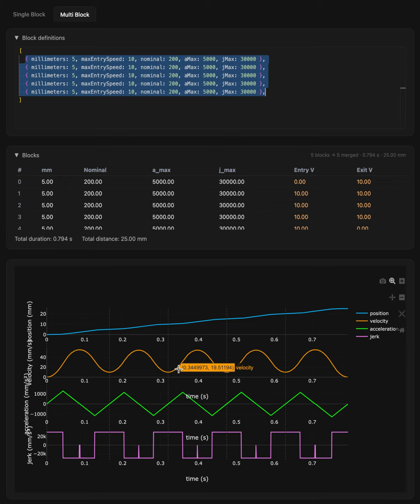in the jerk control case, we not only need to ensure that blocks end at the same speed that the next one starts, feasibility is not about just matching speeds at the junctions, but also accelerations need to couple perfectly between blocks.